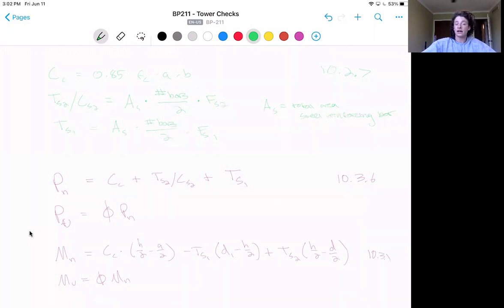So that concludes the calculations for the main body of our interaction diagram. Personally, I like to use an Excel spreadsheet here to calculate one full row of numbers, then drag to vary C from 0 to 30 centimeters and get a full suite of values. In the following sections, we'll discuss the special cases and the maximum and minimum values to help create the nice shape of that interaction diagram.